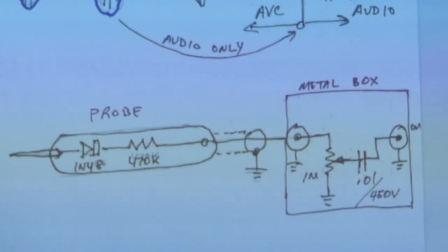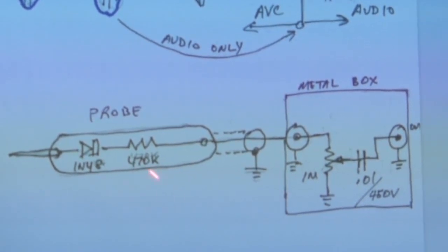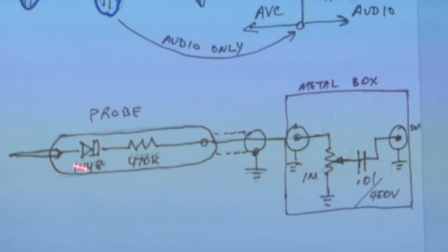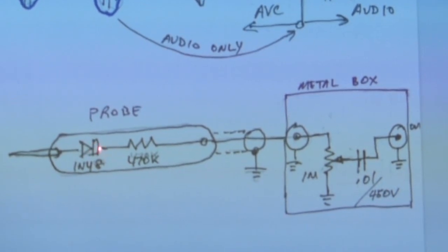Of course, they're all semiconductors, so you don't get a vacuum tube signal tracer out of that. But here's what you can do. You can take this circuit here, you can make your own little probe. Now this is the probe and the components inside of the RF probe. See, it has a germanium diode there. You can make your own probe.